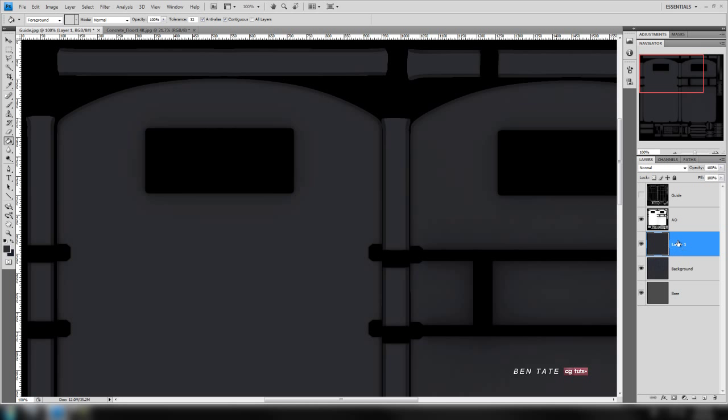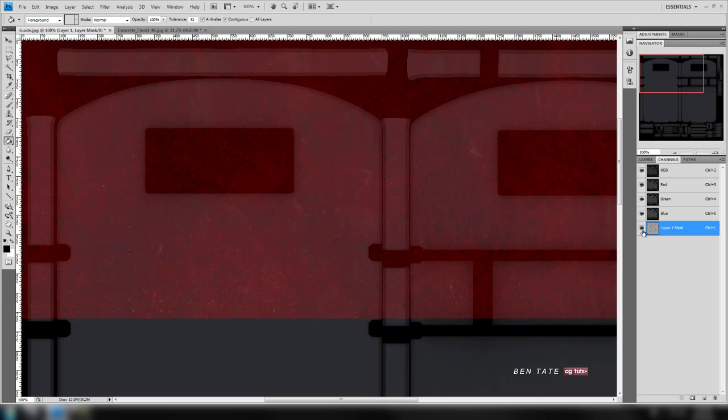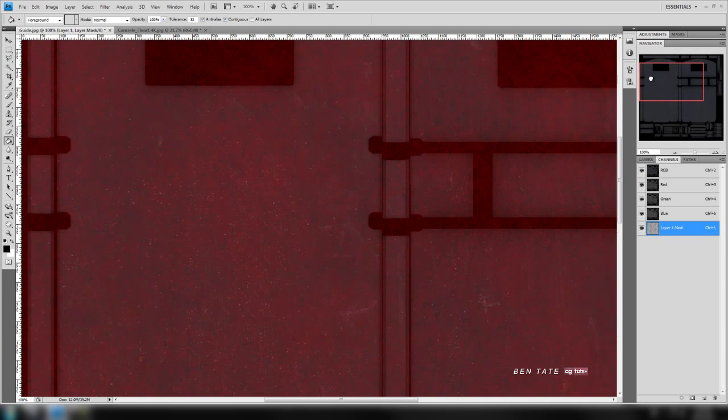Right, and with that color layer selected there, let's go down here and we'll put a quick mask on. Okay, I'm just going to click on the mask box here, go into the channels tab, and we'll turn the mask channel on, and then we're just going to do Control V to paste that in. Okay, and you can see it turn red there in the viewport.